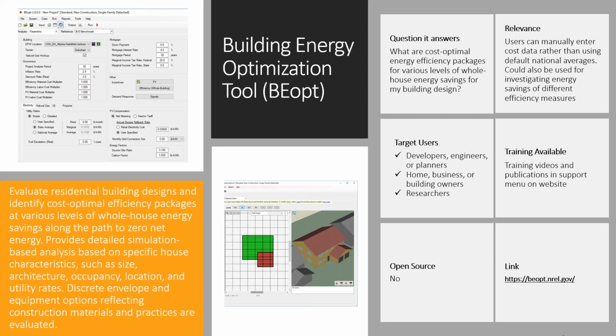So for this example, it was an 1800s house, really inefficient. We did a baseline where we assumed the least efficient HVAC system versus the most efficient, of course. And it picked mini split heat pump, interestingly, as the most cost effective and most efficient HVAC system, plus things like wall insulation levels and different types of LED lighting. And then it said, okay, with this highest efficiency model, you then need 8 kilowatts of PV.